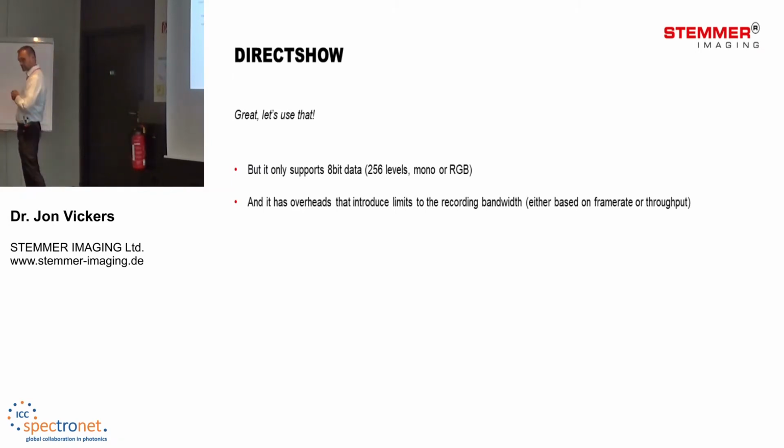But there are problems. And these are problems related to recording. It only supports 8-bit data. So maximum 256 levels, whether it's mono or RGB. And it has some overheads related to the number of files, number of images, so there's some kind of start and stop overhead, but also a maximum recording bandwidth.